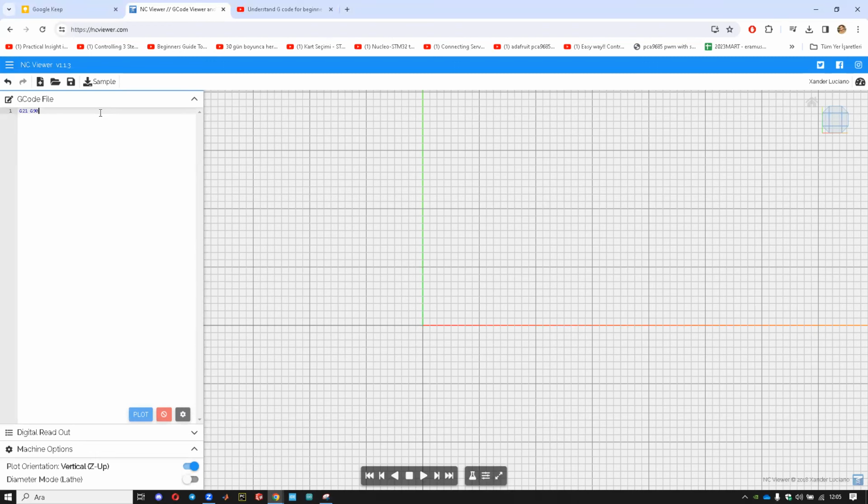What is absolute programming? What is incremental programming? So far you have learned about absolute programming. And we also have incremental programming, which is G91. I'm not going to confuse your minds for now, but at the end of the video, I'm going to talk about incremental programming too. But for now, let's keep it G90.